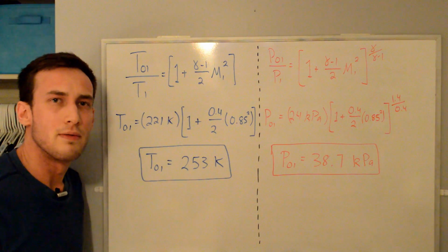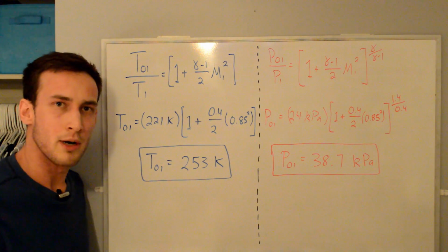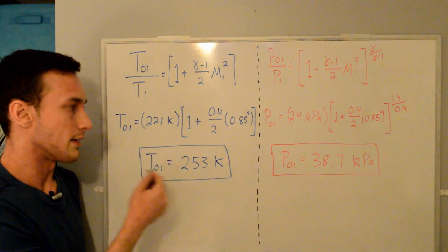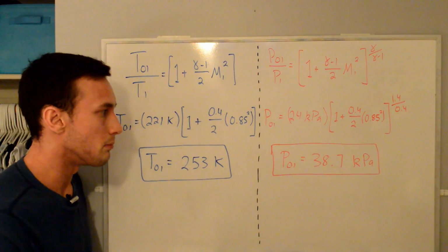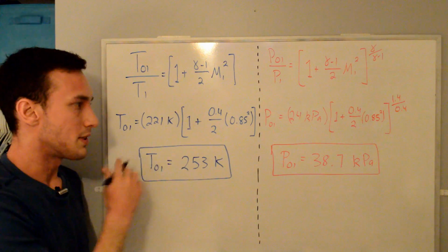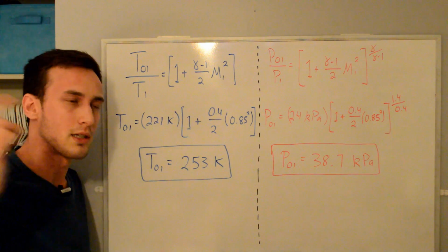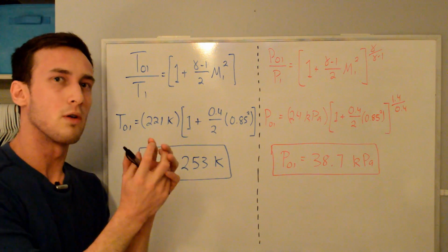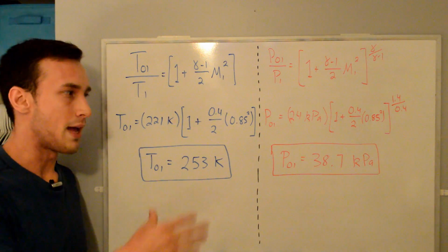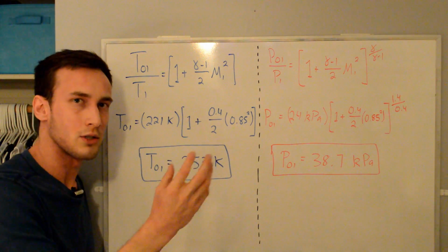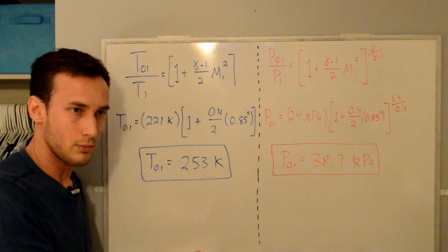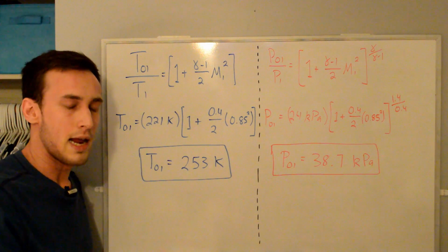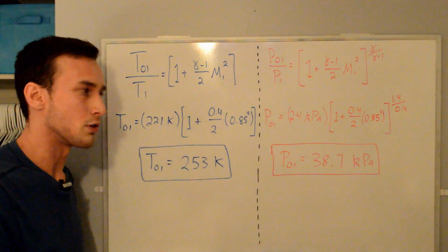The next thing I said that we needed for our analysis are stagnation properties, and they are denoted with the subscript 0. So T01 or P01, both ways are fine. They're stagnation properties, and it's what happens if you take this fluid element that's flowing and isentropically bring it to rest so that it has no more velocity, and it's the conditions that would occur if you brought it to rest isentropically. By isentropically I mean reversible and adiabatic. Reversible meaning there's no losses such as friction or shocks, and the adiabatic portion is that there's no heat transfer, no heat loss or gain.